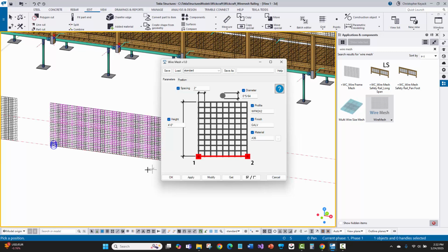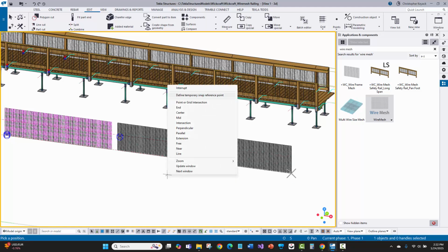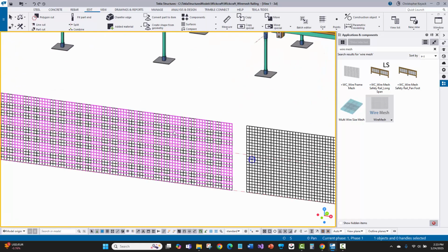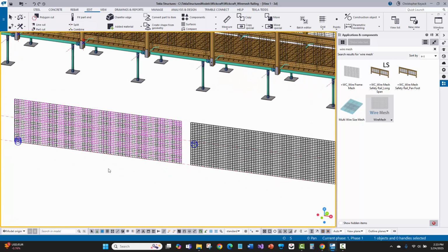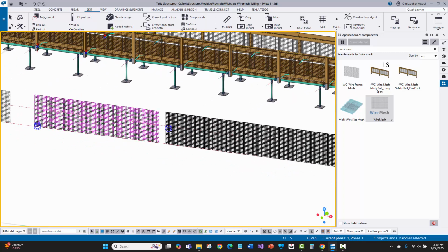Now, sometimes though, due to speed or complexity, custom components just aren't always the best tool, and so then I'll go through and use programming and the API to make a parametric plugin, and that's what I did here. So ultimately, same functionality, but if I come in here and put this in here, it is going to be a lot faster, like 2 seconds to put in even that longer version, because the array macro and everything in the part add that's being done over here is much slower than me doing it in the API. But ultimately I get the same result.